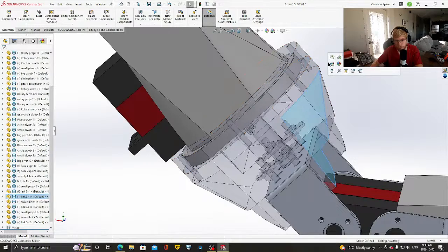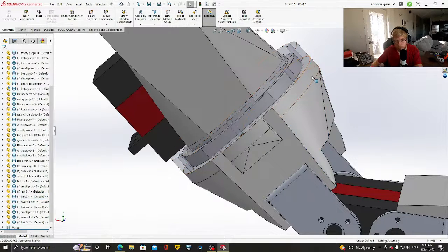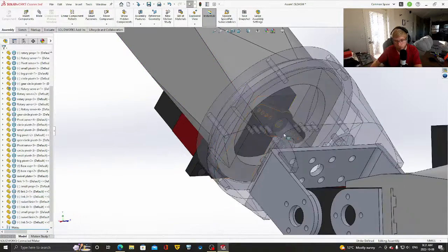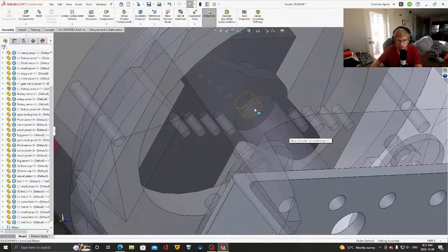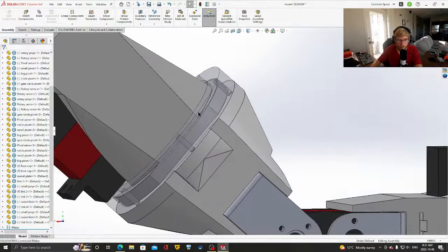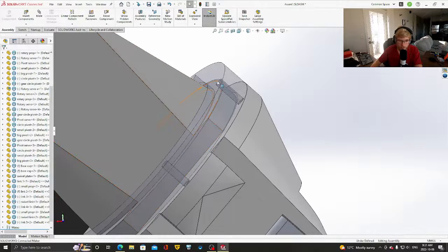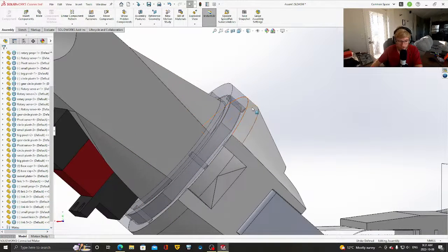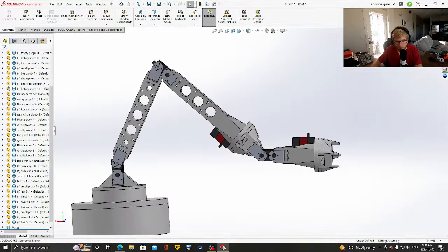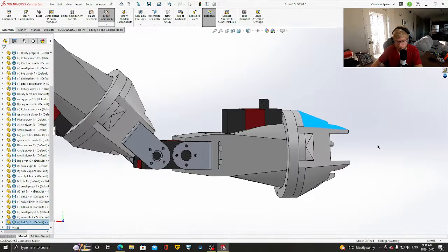And this final coupler will then hold these 2 joints together, because while there is a little screw in these servos that attaches the actual propeller to the servo, I didn't want a whole lot of force being applied to just this one little screw. So with this, any major forces should be applied to the backside of the swivel here and reduce the actual weight on the servo to help keep it from breaking. And so I did that with both of the swivel joints. Both have the same connection.